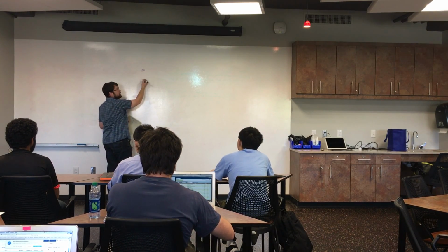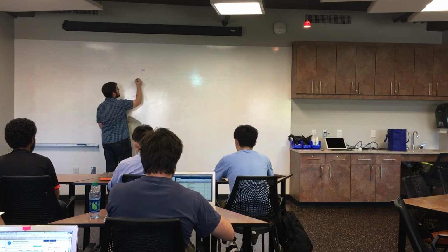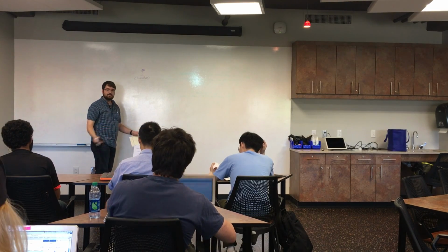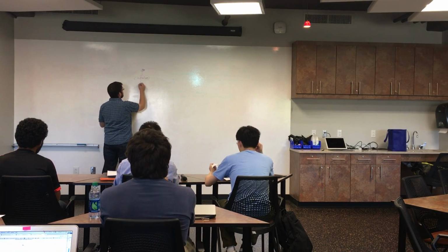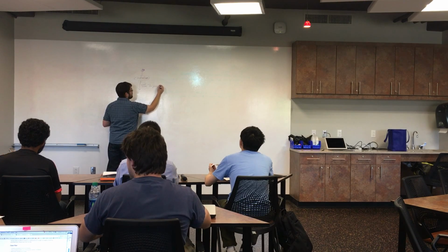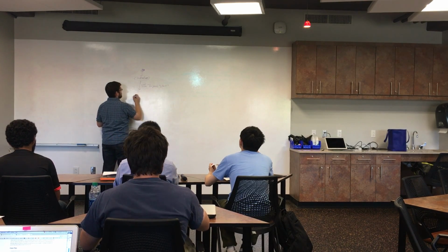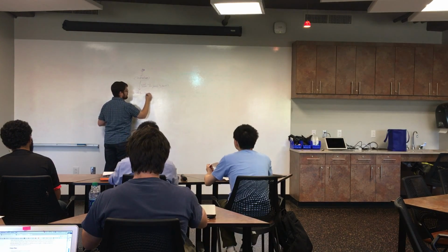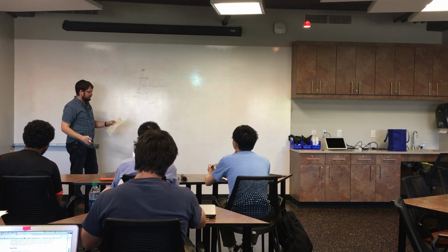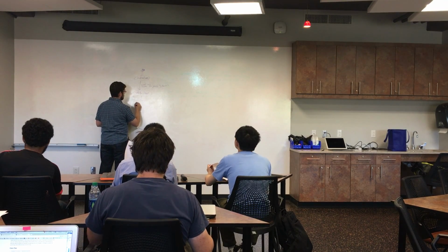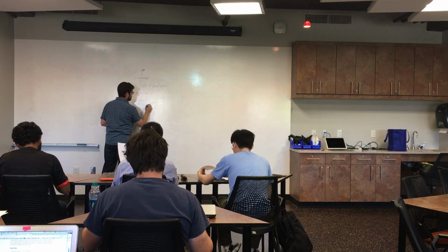I would start my state machine, and then I would go to an initialize state where any startup stuff that needs to be done would happen. And then I would wait on the user to set things and press start. After that, I would do a safety check. And there could be lots of things in there that weren't necessarily in the user story. After we know that it's safe, I called this state source on.